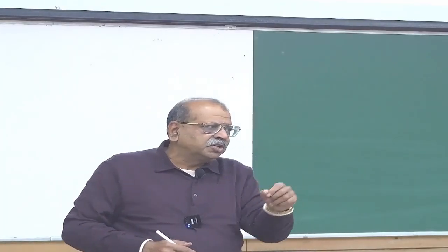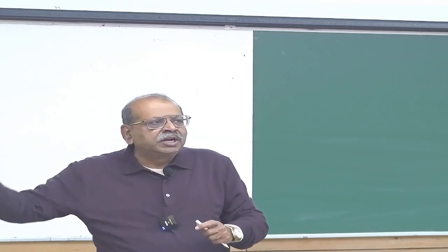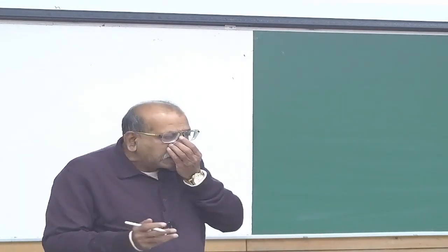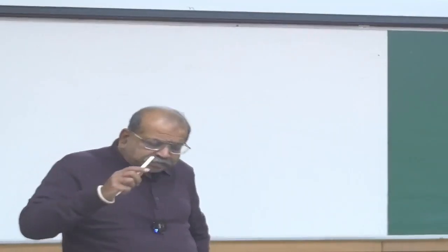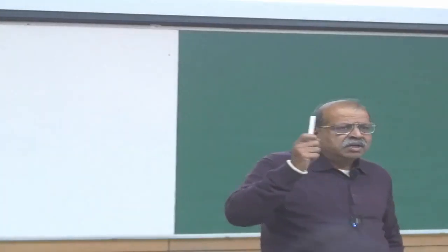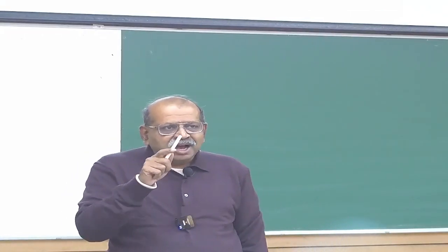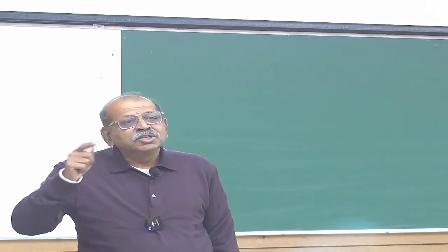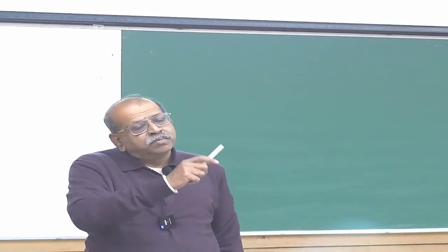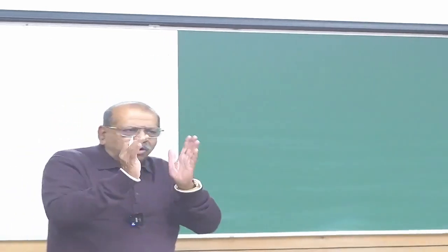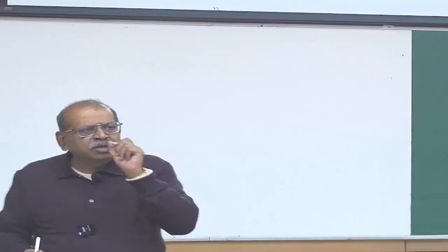about the nomenclature, which solid mechanics texts somehow use only tau for the shear stress and sigma for the normal stress. But other than that, if we look at the notation, another thing you may find if you follow some really classical books: I have used sigma ij, with i for the direction of the force and j for the direction of the area. In some books, they do it in a reverse way, so don't be confused by that. We will follow one consistent notation. We will use the first index for force, second for the area. But it could be done with the other one and it won't make a difference.